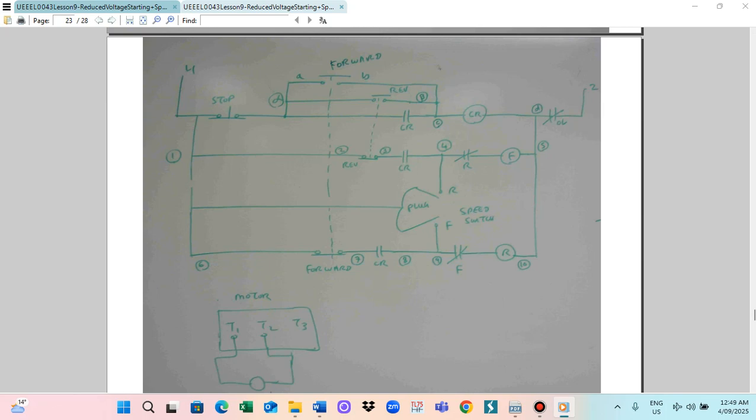So that you don't need to press the motor for the die, so the motor will run. This is the forward, and reverse for the chain. When you press the reverse switch, the current will also flow into 1, 2, 3, 4, and 5, and the forward circuit is cut off. Forward circuit cut off, and the reverse connection will be energized.